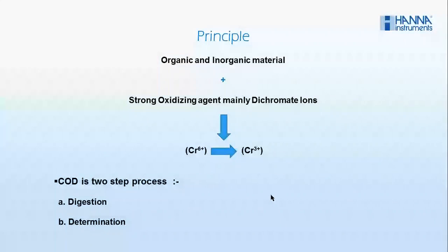COD is the measure of biologically available and inert organic matter that is susceptible to oxidation by a strong oxidizing agent. The US Environmental Protection Agency specifies that the dichromate reflux method is the only method acceptable for reporting purposes. The advantage in using this method is certifiable results as well as high accuracy. COD is used as a measurement of pollution.